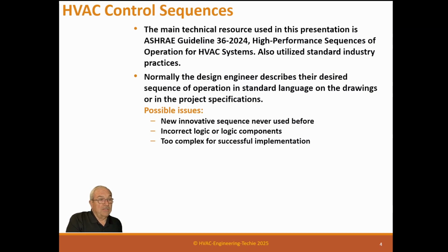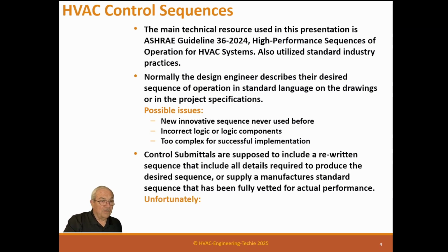And the truth is, there's not many requirements for new sequences. Trust me, we have plenty of sequences out there to do anything you could possibly imagine. So my reference is always to convince the engineer, let's try to use some standard sequences from the manufacturer. They've done them, they've tested them, and they've been tested in the field many, many times over. So that's a good shot those are going to work well.